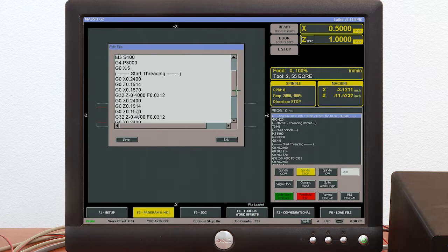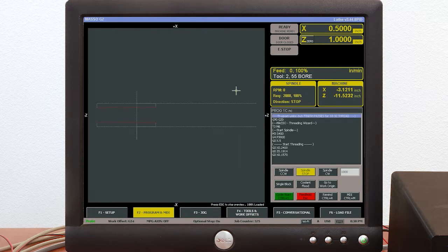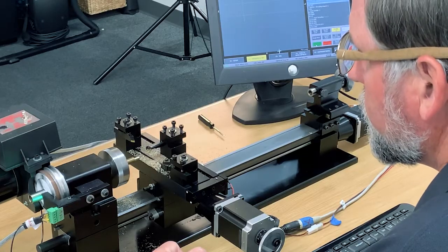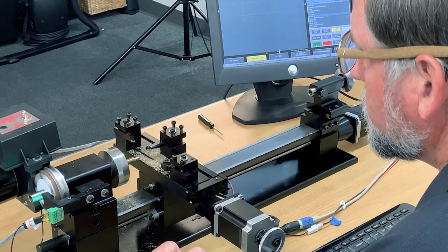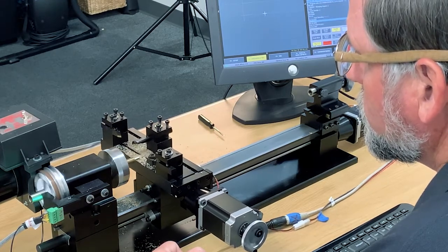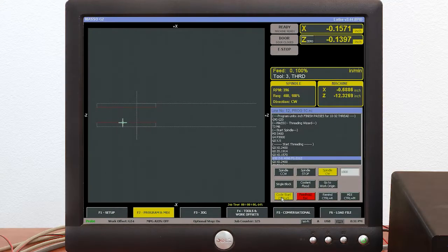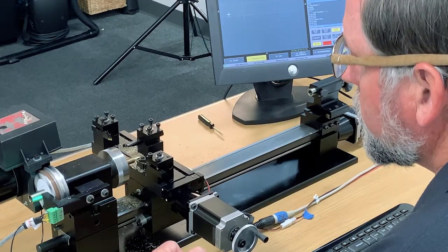It's basically called a spring cut. And if I wanted to change this or add more passes, I could. Right now I'm just going to hit save, and it'll tell me that it's saving, and it's saved. I hit exit. If I had made any changes, RPMs or anything else, it would show here right now. Okay, I'm going to hit rewind again, and I'm just going to run the finished threading cut. Took a slight cut there, and this is the same pass, just a cleanup.